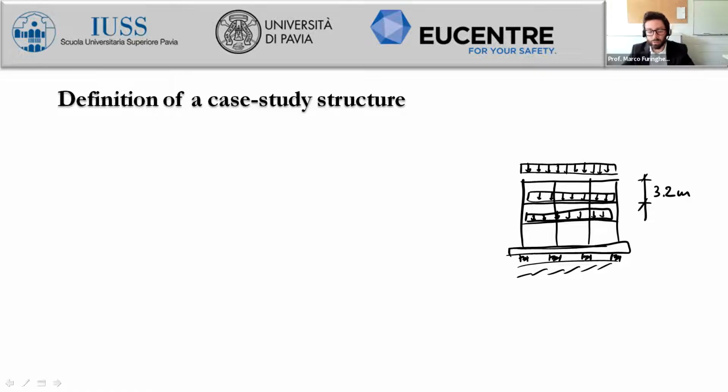What we don't know is actually the permanent load, so the self-weight of the structural components that we are implementing, because what we defined at the beginning as G1K, the permanent structural loads, refers just to the flooring system. This means that at this stage, we don't know the weight of beams and columns. We can compute the weight for the plate, but we still have to design some sizes, some geometrical properties for all the beams and columns.